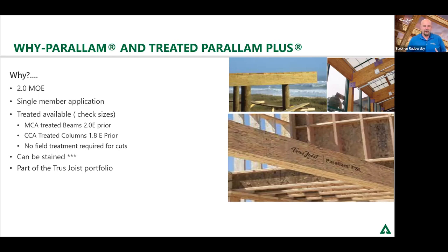When you think about the way fibers are done in structural lumber, when you have a beam, everything's running kind of horizontal, so you have that ability to bend. When you're doing a column, think of straws. If you were to take a pack of straws, how hard it is to squash them when you're standing on top of them. And that's why you don't need the stiffness necessarily in the column.